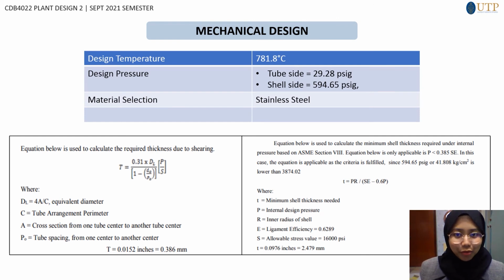Different pressure and non-pressure components are designed in the mechanical design of a heat exchanger. The mechanical design of a heat exchanger determines its structural rigidity and ability to provide acceptable service. Mechanical design is often carried out in accordance with design standards and rules. From the calculation that has been done, the thickness for the tube sheet, shell, and flat cover will be determined.